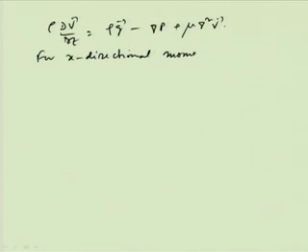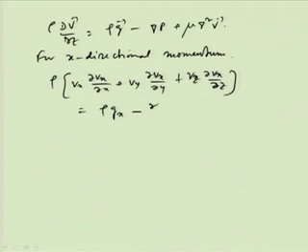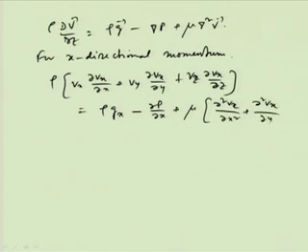momentum at steady state, when del Vx by del t equals 0, rho into Vx into del Vx by del x plus Vy into del Vx by del y plus Vz into del Vx by del z becomes rho Gx minus del p by del x plus mu into del square Vx by del x square plus del square Vx by del y square plus del square Vx by del z square.